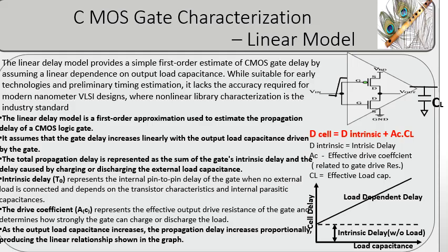However, actual CMOS gate behavior is highly nonlinear, with delay and power also depending on input transition time, supply voltage, process variations, and temperature. Therefore, modern VLSI design flows replace this linear approximation with nonlinear characterized library models for accurate timing and power verification.